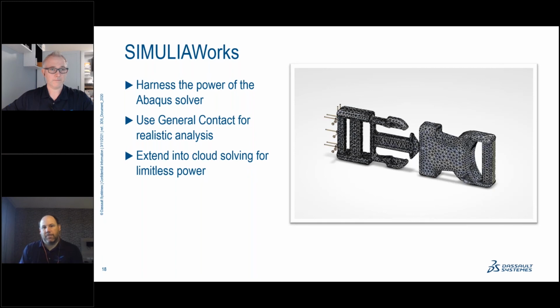So the other two big characteristics of the SOLIDWORKS tools, these more advanced analysis packages, one is the concept of general contact. In SOLIDWORKS Simulation and most other analysis tools, if you've got two parts coming together, you need to tell the software which faces on each part are going to interact when they meet. If you've got a lot of parts moving together in a complex way, that can be a lot of selections, right? And if you miss one, you get the wrong behavior.